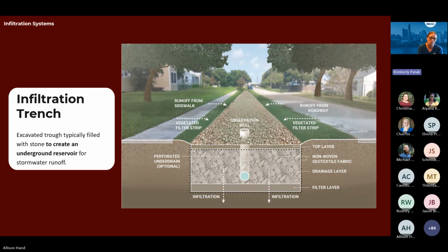And sometimes if you don't have more of a sheet flow condition, but you still want to use an infiltration trench, you can also tie in a storm drain system, like a pipe outfall into the sidewall of the infiltration trench. And oftentimes for that, you really need to make sure that you've got an upstream control, like maybe a rain garden or a detention pond, to be able to trap that debris upstream, because you really don't want those fine particulates and trash coming into the trench.